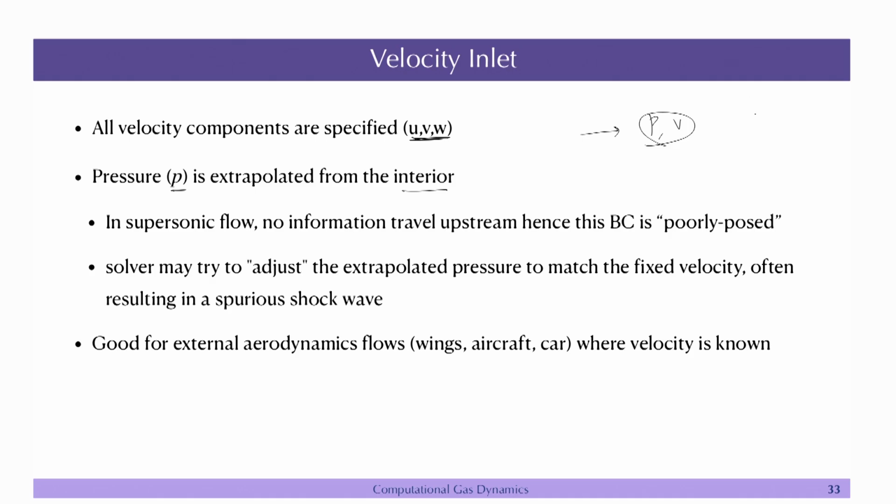One is that, for example, let us say you put a pressure, or put a pressure as a boundary condition. Specify means it is fixed, you cannot change it, the code also cannot change it, that is fixed on the boundary. Okay. And let us say your velocity is also fixed, okay. They are both specified, you specified both of these things.